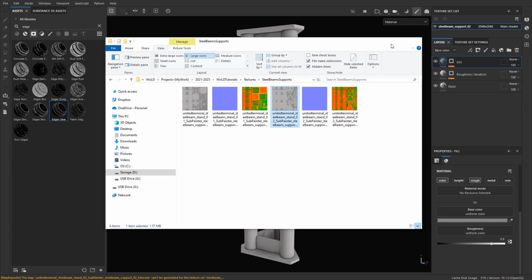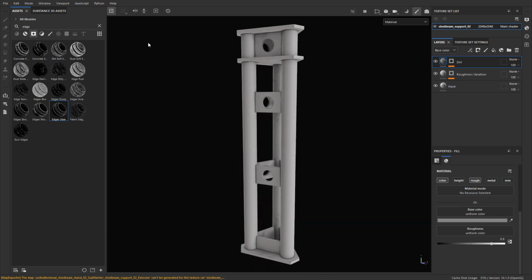And then you repeat the same steps for the other meshes you brought in. So this way it allows you to quickly reuse and rebake your mesh maps, change the name, save the textures, and save a lot of time in the process. Perfect way for when you have the same theme meshes and you just need to reapply the textures and the layers to the new set, and a great way of reusing what you already did.